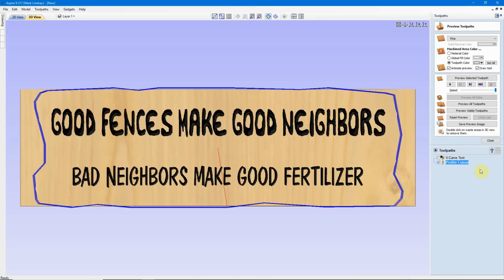There's our toolpath. Now, something to notice is, in these areas here where I didn't make the modification where this is going to cut out to the full width, remember, because we're cutting to the outside of the vector, the bit is actually probably not even going to touch the edge of the wood right here. And that's okay because I want that straight line. If it does touch it, fine. Just be aware that sometimes the bit will leave the material and then come back in, depending upon how we have our profile cutout toolpath machined.